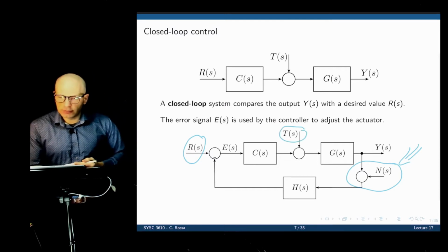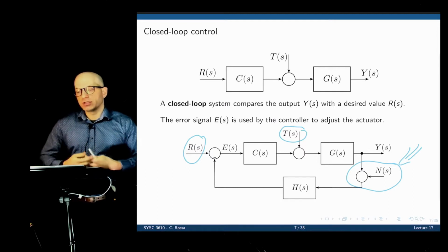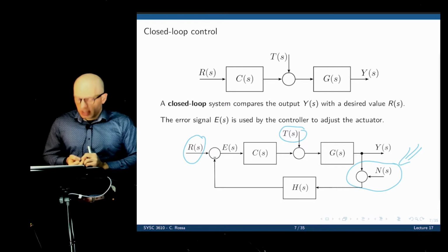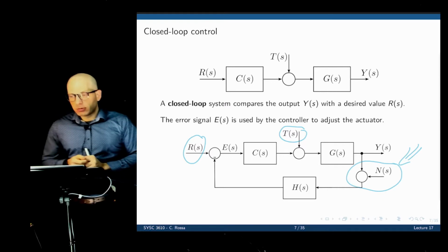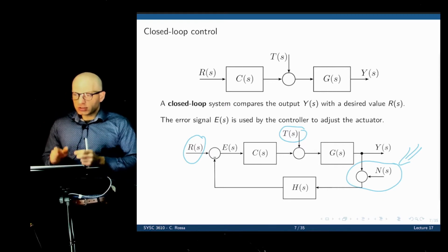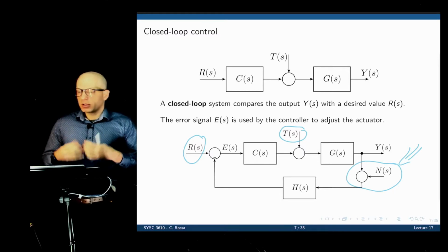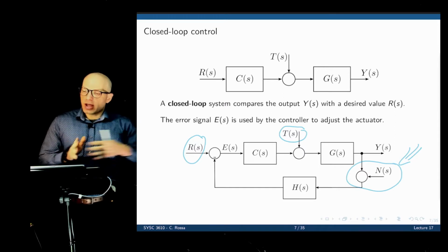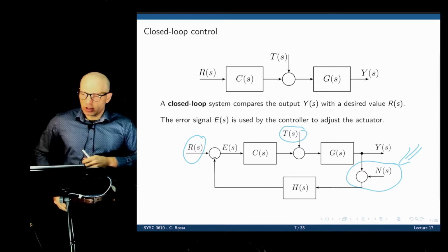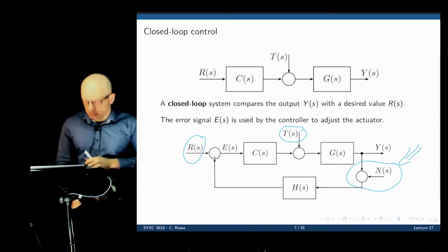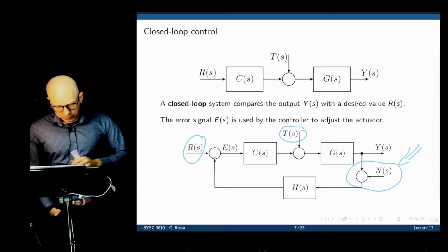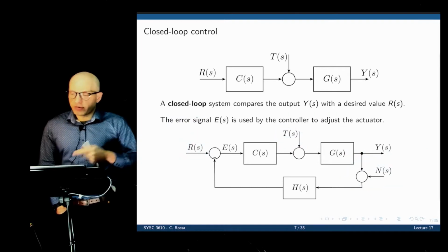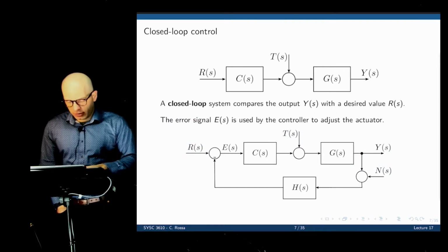How do we calculate the final output of this system now? Well, there are 3 inputs, but we are dealing with linear time invariant systems. So the principle of superposition applies. If you take one input at a time and calculate its output, we can then add all 3, and that will be the output of the system when all 3 inputs operate concurrently. And this, again, only works provided that the system is a linear time invariant system.